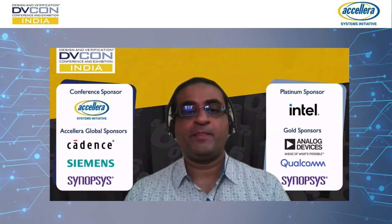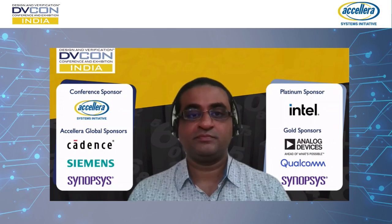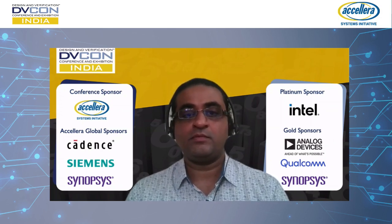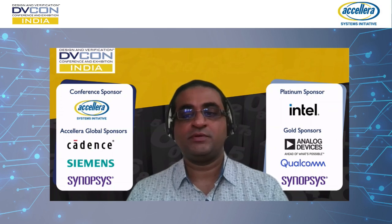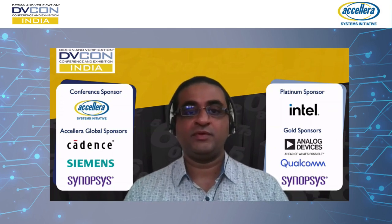The bigger the size of the SoC, the bigger the runtime is. When you try to capture a lot of interfaces, for us it's an application processor kind of design where our runtimes vary somewhere close to 4 hours, and with power test cases it can go up to days. That's the scale we are trying to conquer.